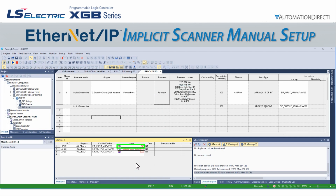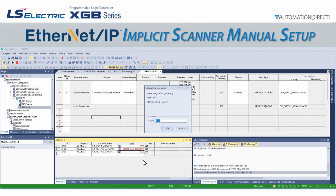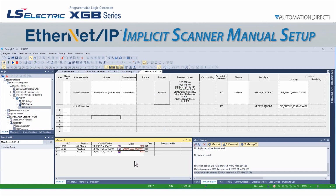and sure enough, we see the frequency feedback increasing as the drive accelerates. And there it stopped at 60. Let's change our frequency command to 40 Hz. And the drive went down to 40. And now let's turn off bit 1 and turn on bit 0 of the command word to put the drive back into stop mode. And the drive executes a deceleration back down to 0 Hz.